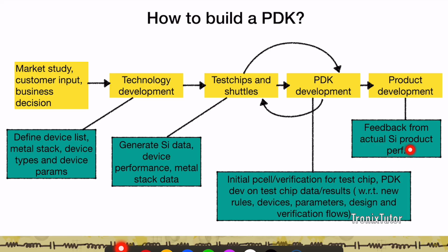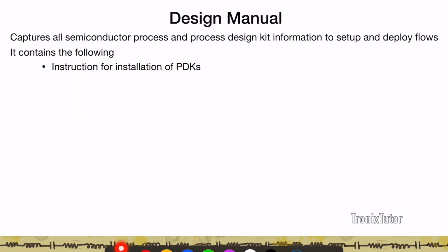And so you actually get feedback from silicon, from that particular product. It's an iterative process: you need to go through a couple of product cycles, a couple of test chips, multiple back and forth. So this PDK, if you think about it, has different versions. A foundry, when it initially starts, is going to release a PDK with a lower confidence. And as the foundry learns more from silicon and does a lot more experimentation, as it begins to close the gap between the targets and what actual silicon is going to provide, the PDKs become more predictable, and so the quality of the PDK improves.